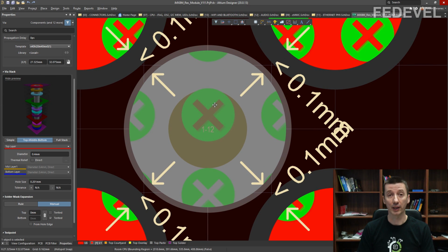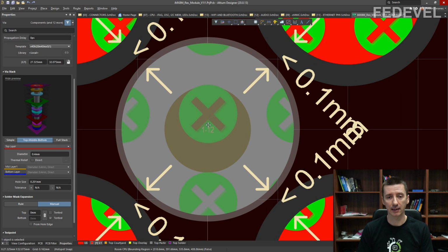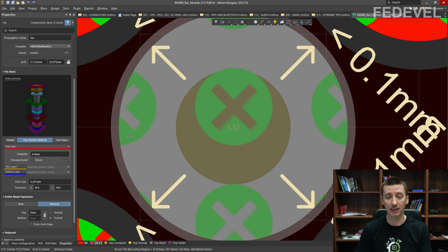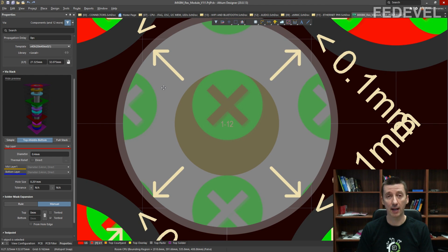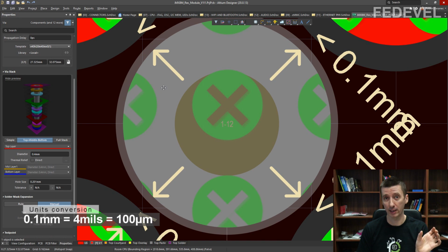Basically, we were speaking about the ring. The ring in a via is the part of the via, the size of the ring is the distance between the edge of the hole in the via and the end of the via. Okay, so this is the hole in the via, this is the ring. And as Mike explained, the standard smallest width of the ring they would like to have is, do you remember? 100 micrometers.